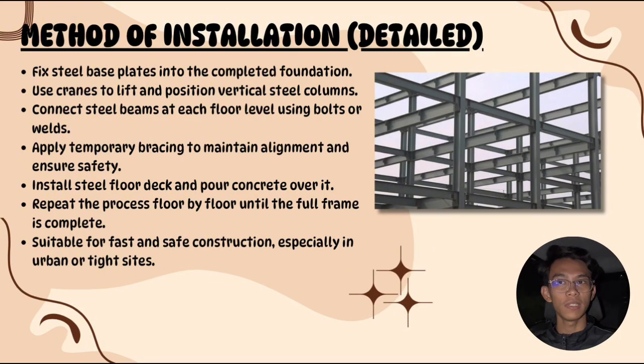Next, the detailed method of installation. Fix the steel base plate into the completed foundation. Use a crane to lift and position the vertical steel columns. Connect steel beams at each floor level using bolts and welding. Apply temporary bracing to maintain alignment and ensure safety. Install the steel floor deck and pour concrete over it. Repeat the process floor by floor until the full frame is complete, suitable for fast and safe construction, especially in